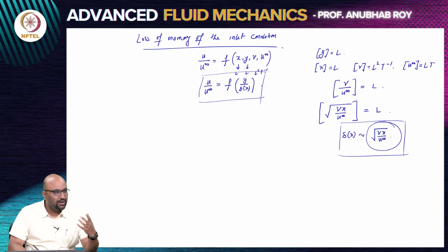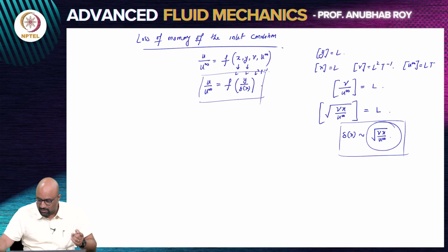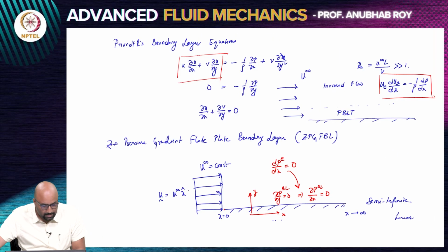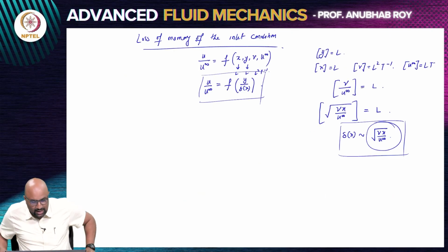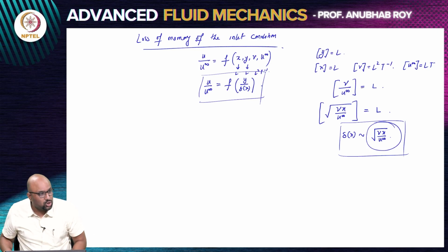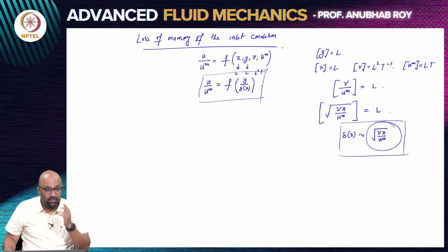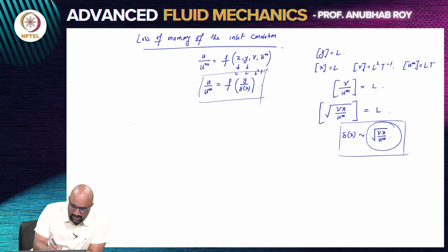The governing partial differential equation that we have is Prandtl's boundary layer equation. We are going to seek solutions for this equation by arguing that there is no inherent length scale in either x or y. So that is the justification. You use the dimensional argument to say that the solution should take this particular form, and now we will formally get what delta of x is. So our starting point is the following. We will define a similarity variable which is y by delta of x.